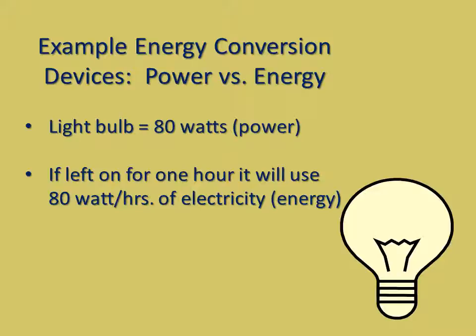It's the instantaneous amount of energy that it would use once it's turned on. And if we leave that on for 1 hour, then the energy that would be consumed, the electricity, would be 80 watt hours.